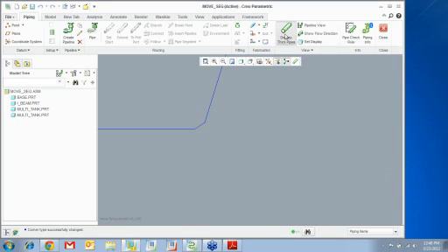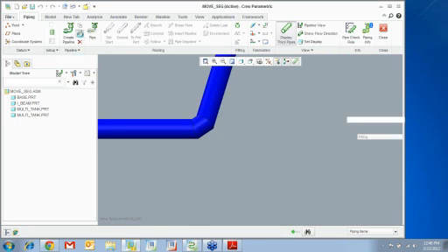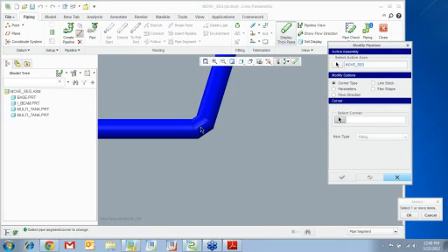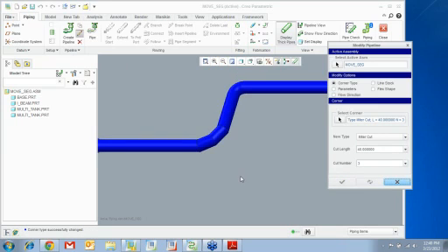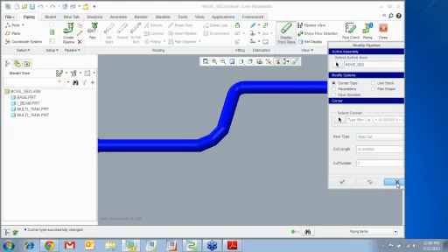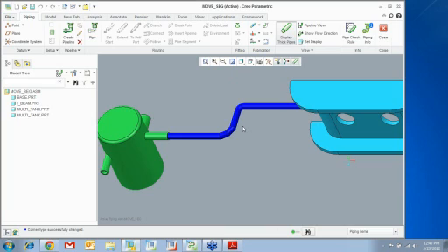and then you can do thick pipes. You can go edit, pick that, okay. I want 3 miters of 40 each. So you can see that, right? So you can edit all these within a pipeline real quick. Okay.